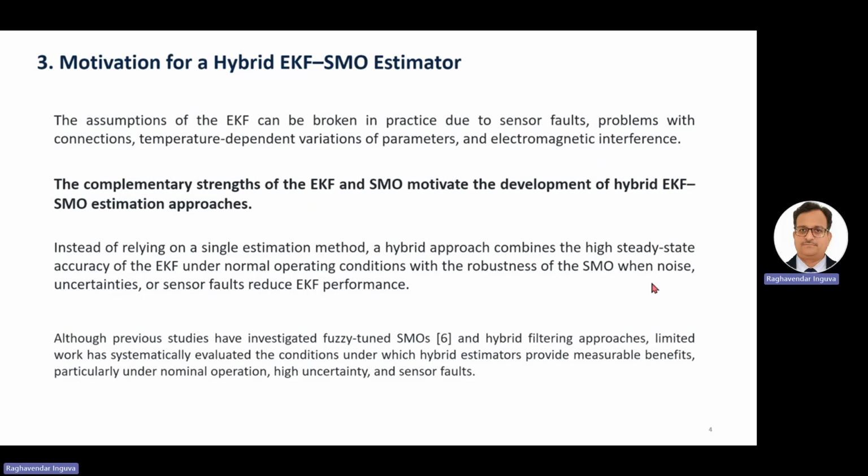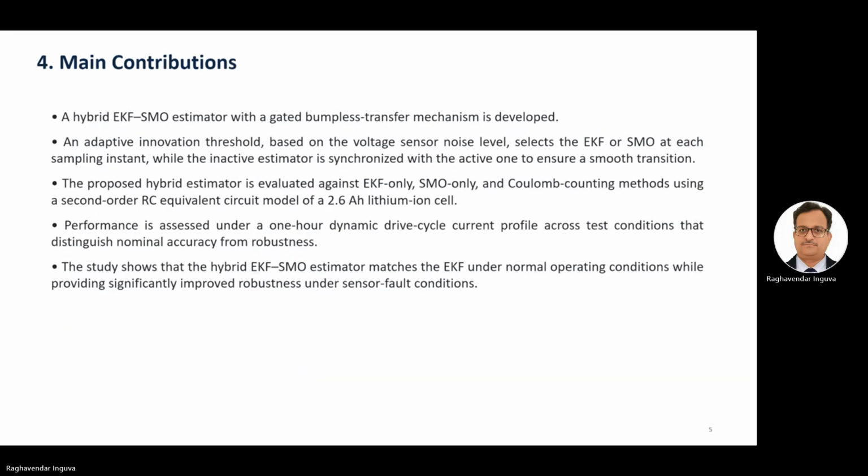SMO is used when there is noise and there are uncertainties or sensor faults. In those conditions, EKF performance will reduce, so we will switch to SMO in such conditions. So the main contribution of this paper is our hybrid EKF SMO estimator with a gated bumpless transfer.